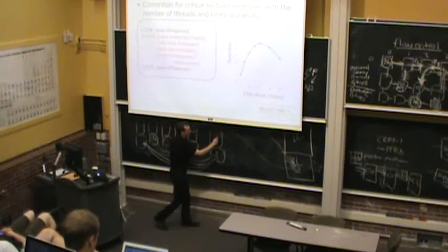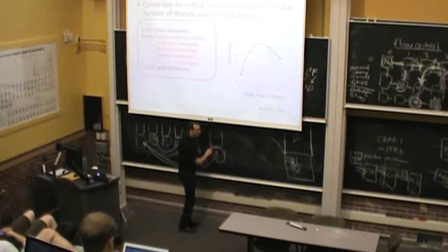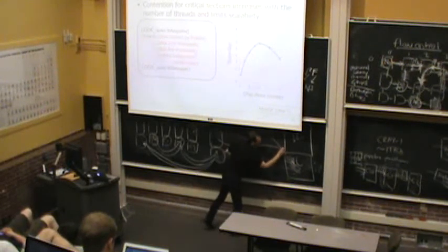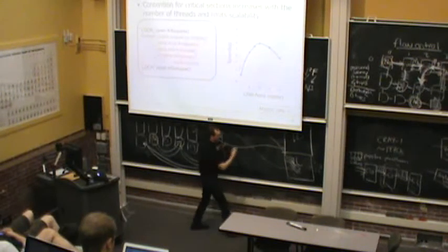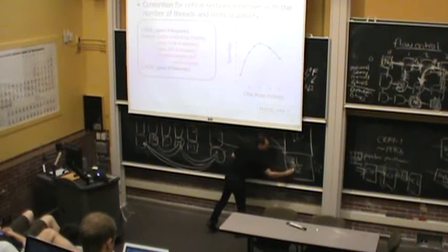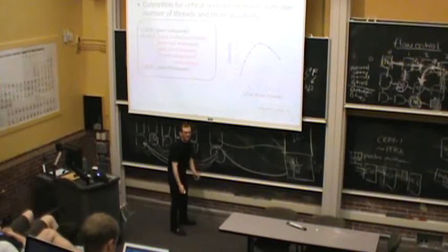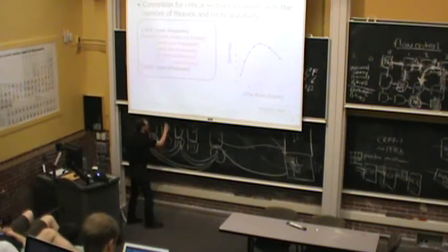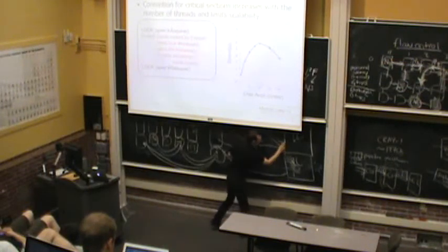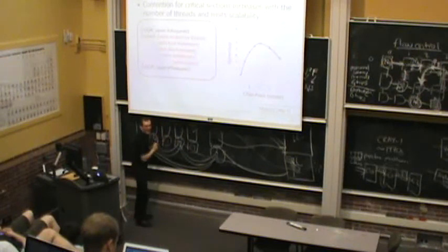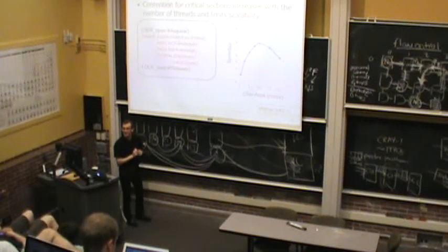Next thread gets to the critical section. It doesn't pull the lock into its cache. It says, large core, execute this critical section for me. The large core executes the critical section for the thread and sends a message saying, thread, I'm done, keep going. Another thread gets to the critical section. This core sends a message, large core, execute for me, and the large core, when it's done, sends a message back. You get the idea, right?